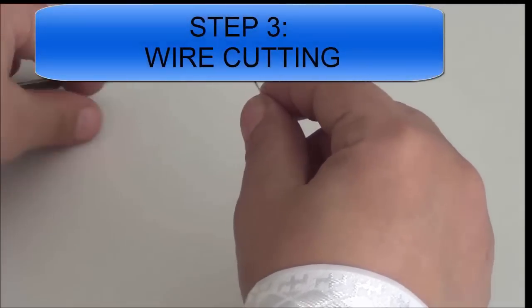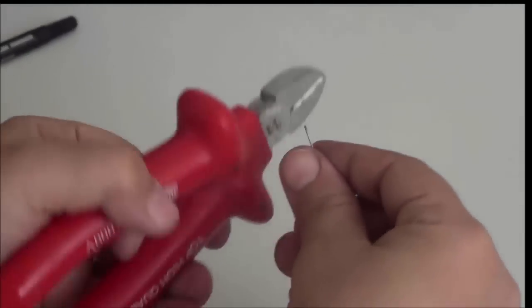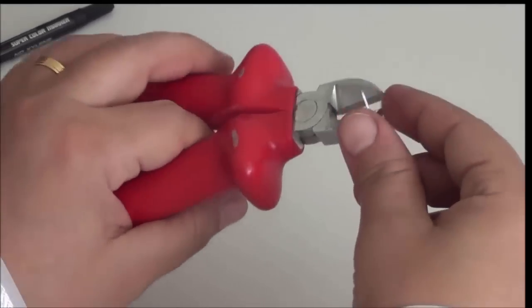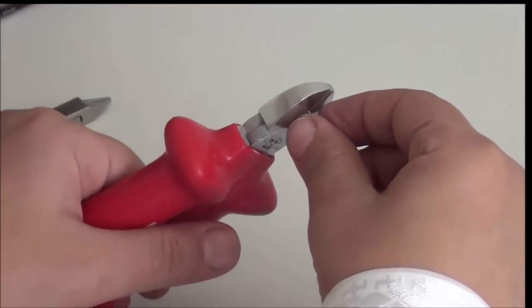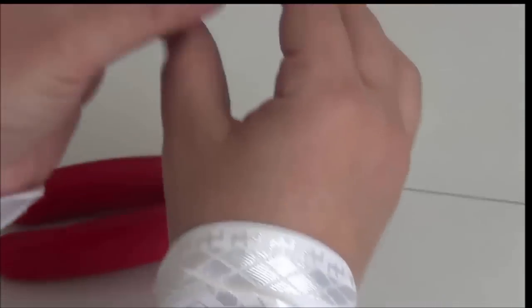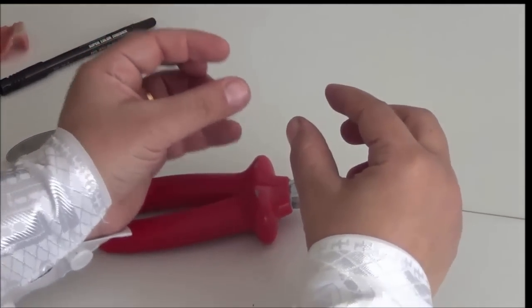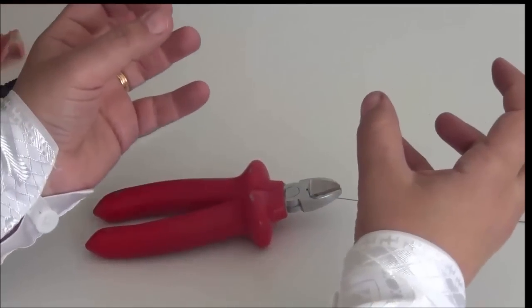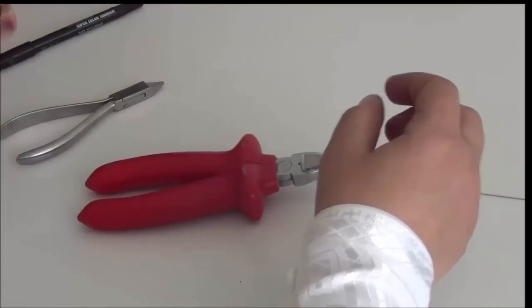Also, for safety issues during using the cutter, as long as we're talking about safety now, the cutters are designed to be like a wedge. So they pierce inside the alloy. And once they cut, they will go inside in a manner that the wire can go suddenly away from each other. Now the small piece of this wire, once it's separated in this sudden motion by the wedges of the cutter, it might fly away.